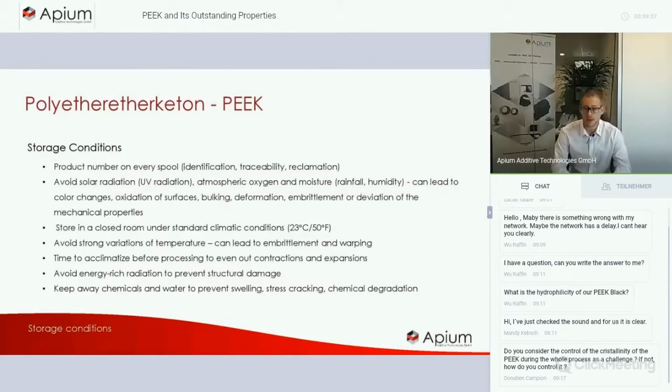Our strategy to overcome this is we offer right now drying systems that can be placed next to our printer, and therefore we make sure that the material that comes into the printer is already dried, and you have a very good part that comes out in the end. It is also very beneficial for the layer adhesion.